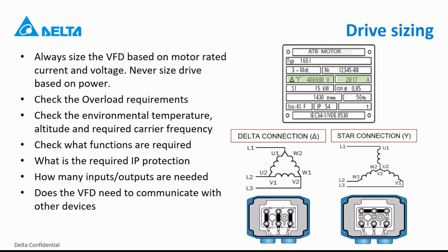Also important is to check if the drive has to communicate with other devices, and what communication protocol needs to be supported. And also very important is to check if there are any requirements from the application in terms of total harmonic distortion or electromagnetic compatibility.